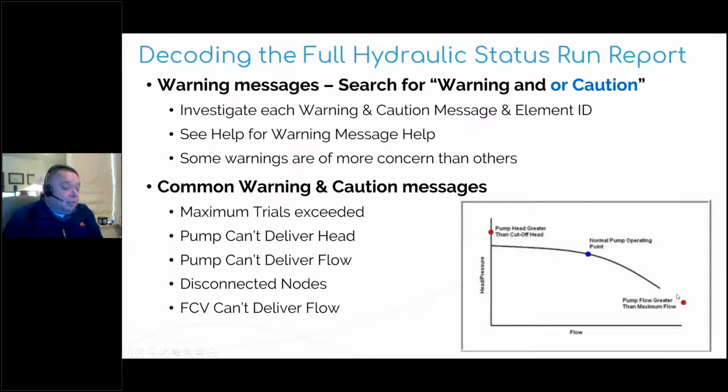That's important mostly because it's telling you, hey, I'm estimating what the pump curve looks like after this last point. I'm taking the last 2 points, drawing a straight line and estimating that out, but that may not be a great assumption. If it's close to the end, it's probably fine, but if it's way beyond that last point, it's probably not.